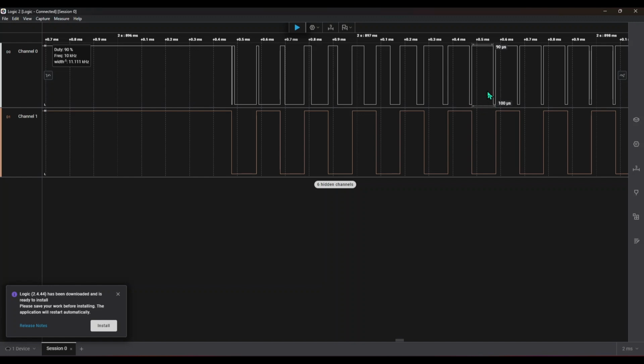So the PWM counter is currently midway through the period that was set up with 8,100, which is 90%. That period completes normally showing 90%, and then from the next period onwards the duty register holds 9,000. That is 100%. But by the time that 100% period starts, the DMA is already idle and no more updates happen. So what you are seeing on the logic analyzer is the 9th value of 90% completing its full period visibly, and then the signal locking at whatever the last loaded value was. This is a classic DMA and PWM period boundary timing behavior.